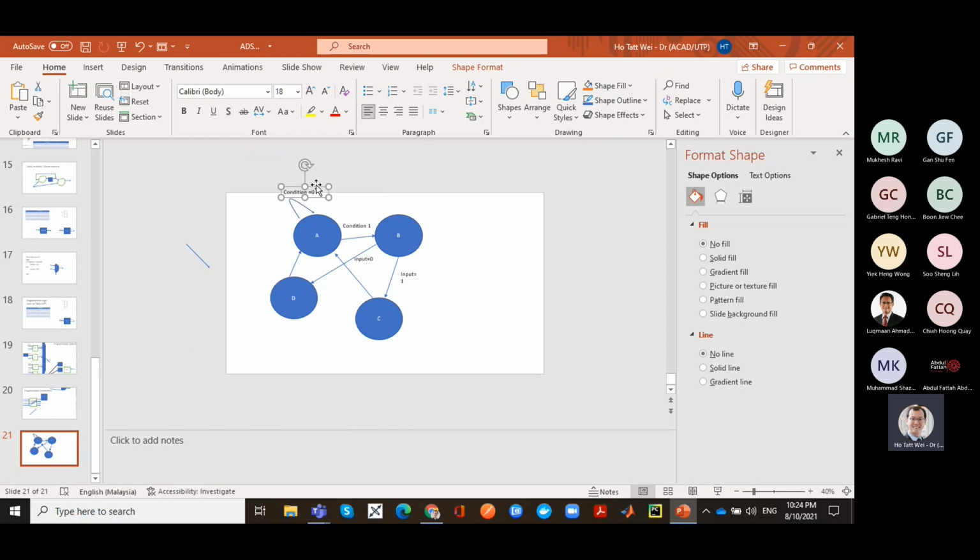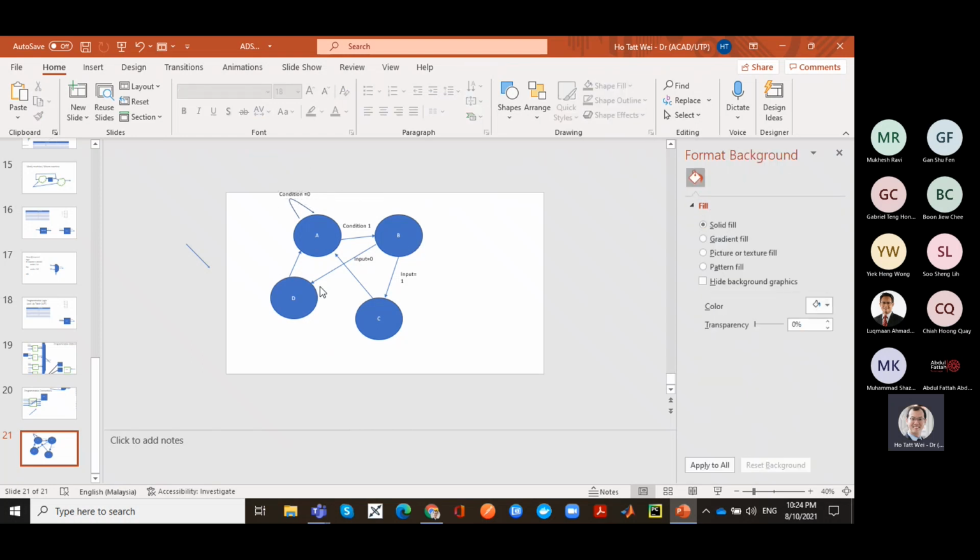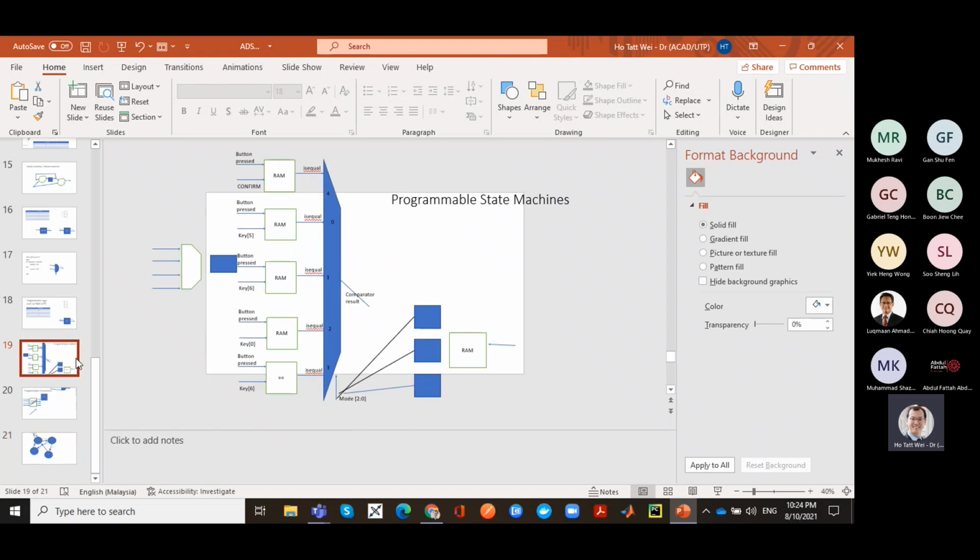Useful state transitions are like that because, for example, you might be used to RISC microprocessors, where one of the defining features is that every instruction will execute in one clock cycle. But when you go to more complex operations, like a multiplication or division operation, you will find that sometimes the division or the multiplication doesn't complete in one clock cycle.